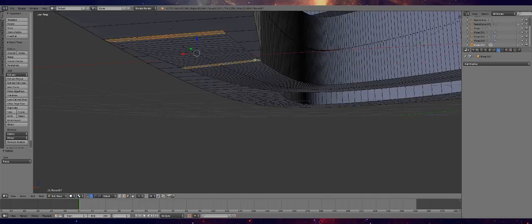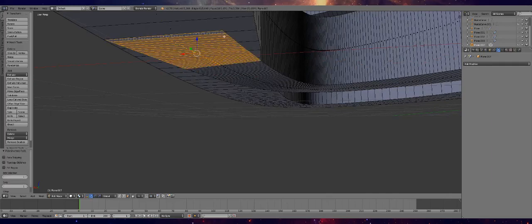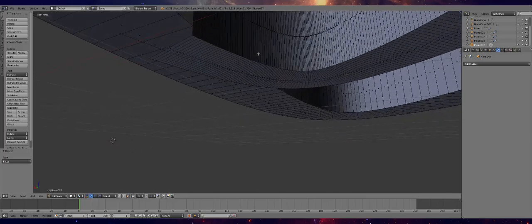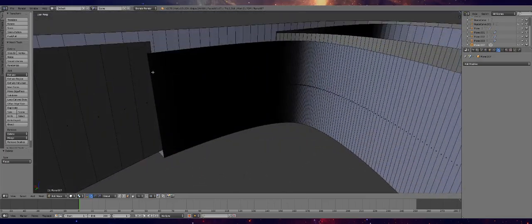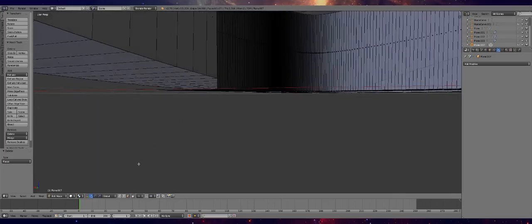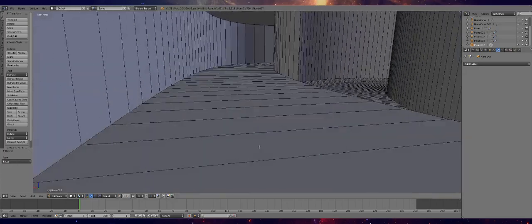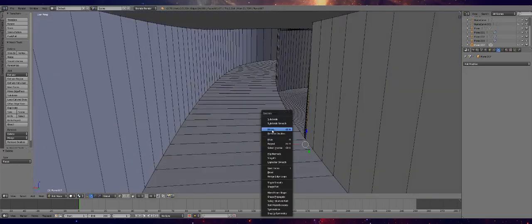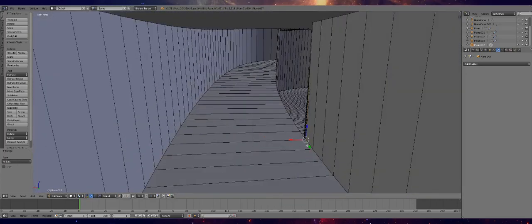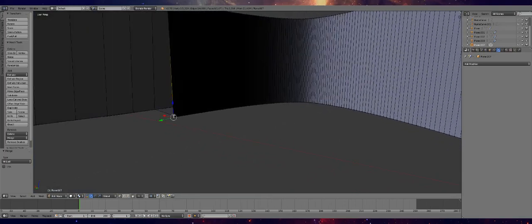I'm going to destroy all the ones that are 100% out, and keep the ones on the closer side here because we want that. Now I'm going to select this edge and this edge, and if I press merge at last, I can see this bumped up, right?